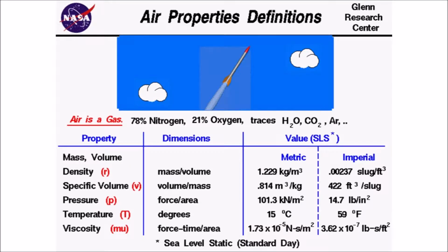Standard is a term used in meteorology to refer to the temperature or the pressure, depending on the context. Standard temperature is 15 degrees Celsius at sea level pressure altitude and decreases by 2 degrees Celsius for each 1,000 feet of altitude gained. Pressure altitude is the altitude read from an altimeter when the altimeter's barometric scale has been set to 29.92 inches of mercury. 29.92 inches of mercury is also referred to as a standard pressure.